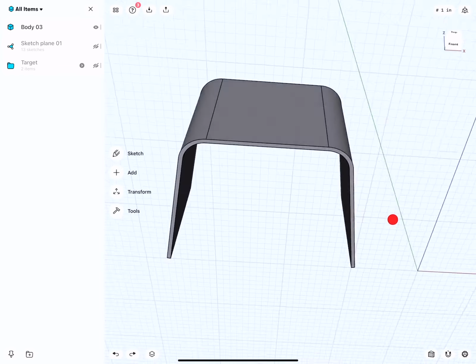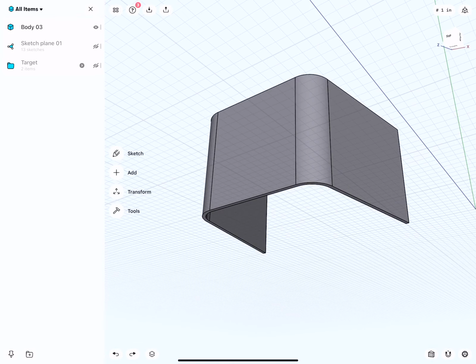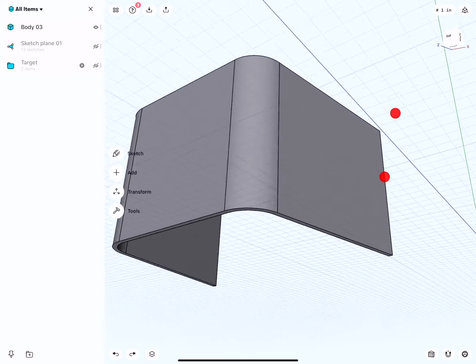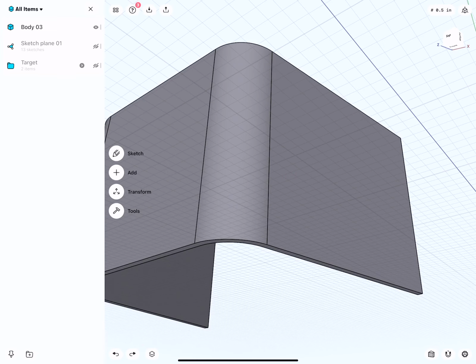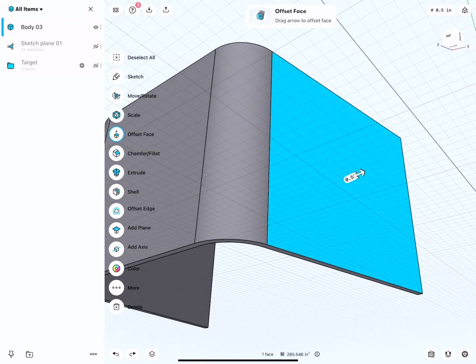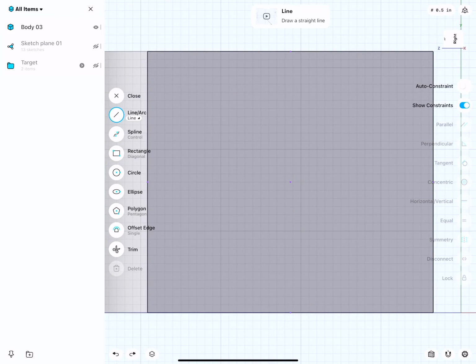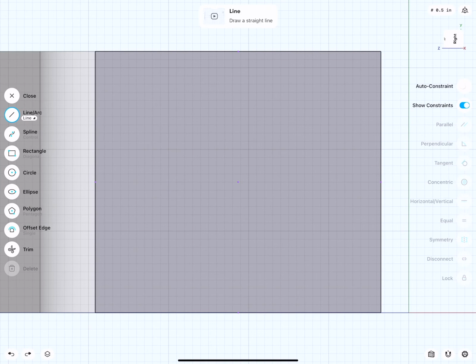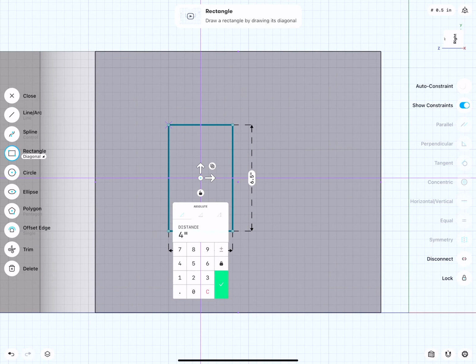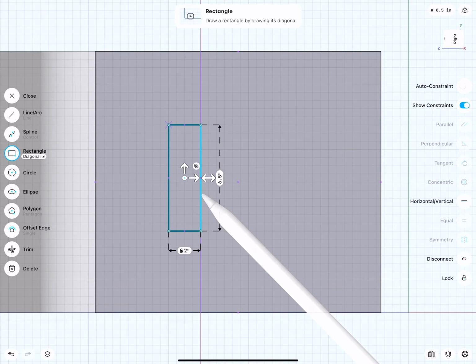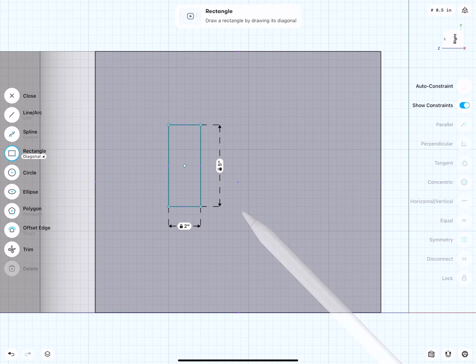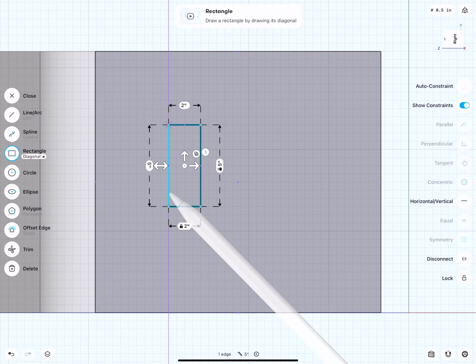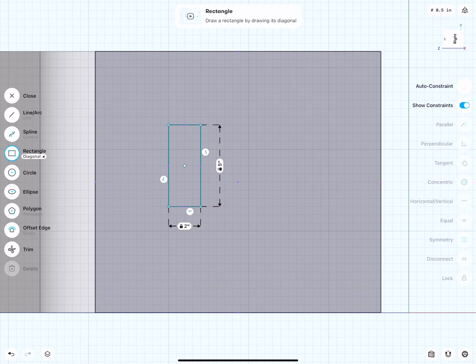I'm going to go back to the original dimension, because at this point now we can take a look at adding the handles on the side, the openings. Okay, so with the pencil we select one side, with the finger we double tap, then Shapr will go into this view perpendicular to the face, and we can start sketching. Ergonomically, for a hand opening, we might need just a rectangle that is 2 inches by 5 inches. Very good. I can make also these edges horizontal and vertical.